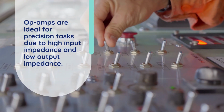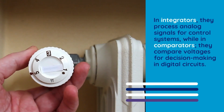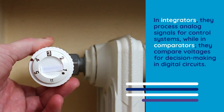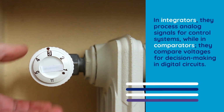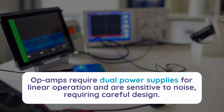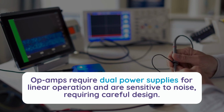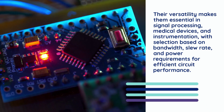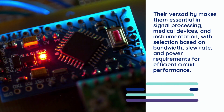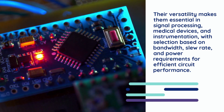Op-amps are ideal for precision tasks due to high input impedance and low output impedance. In integrators, they process analog signals for control systems, while in comparators, they compare voltages for decision-making in digital circuits. Op-amps require dual power supplies for linear operation and are sensitive to noise, requiring careful design. Their versatility makes them essential in signal processing, medical devices, and instrumentation, with selection based on bandwidth, slew rate, and power requirements for efficient circuit performance.